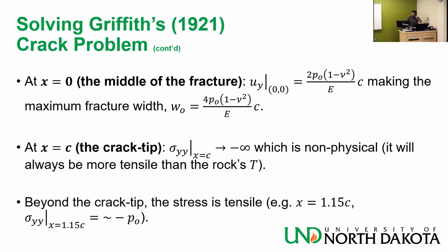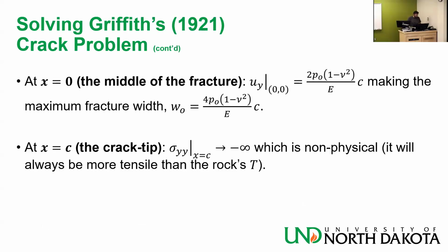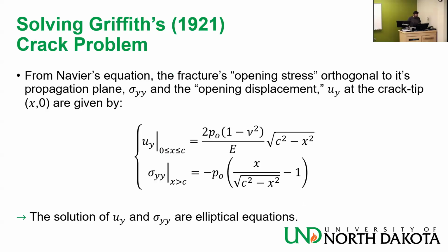For example, at x equals 1.15 C, that's like 15% further than the fracture half length, than the crack tip, I get something like the stress would be minus P net, basically, which is a logical value.